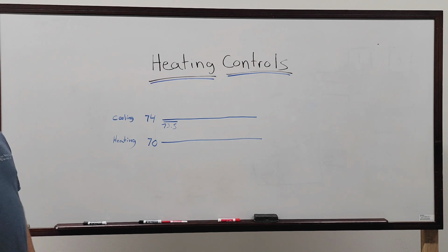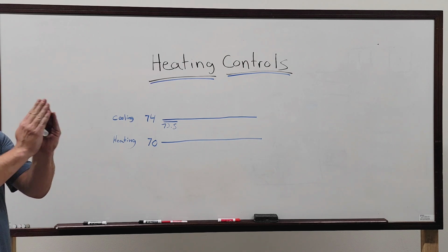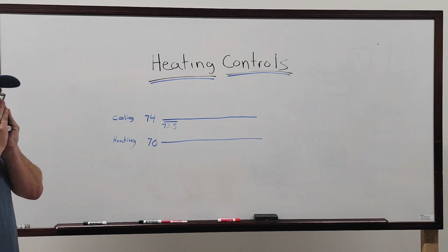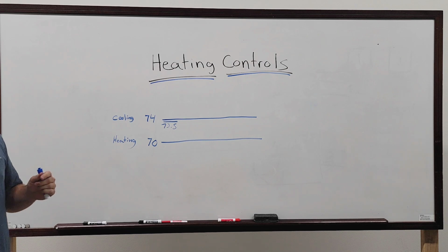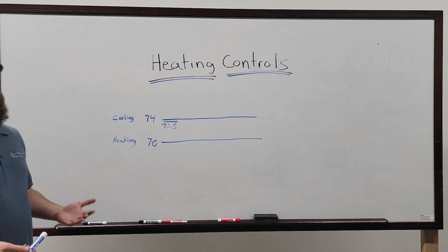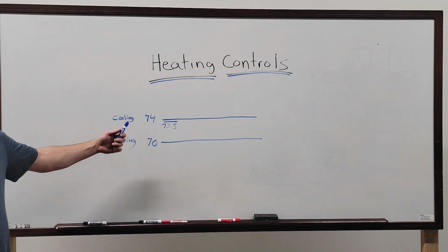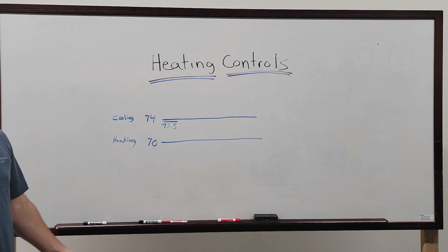So you're saying blowing on the thermostat is not really a great way to test that. I mean, yeah, it can get it to go to cooling. If it's like at 71, I'm blowing on the thermostat trying to get it hotter, because it's reacting so quickly. It can. Yeah, no, 100%. A lot of times you can put your hands over a thermostat and blow into it. You have to do it for 30 seconds or a minute, but it is a way to trigger it on. But if you have access to the system, I would drop the set point. That's gonna be a lot better.